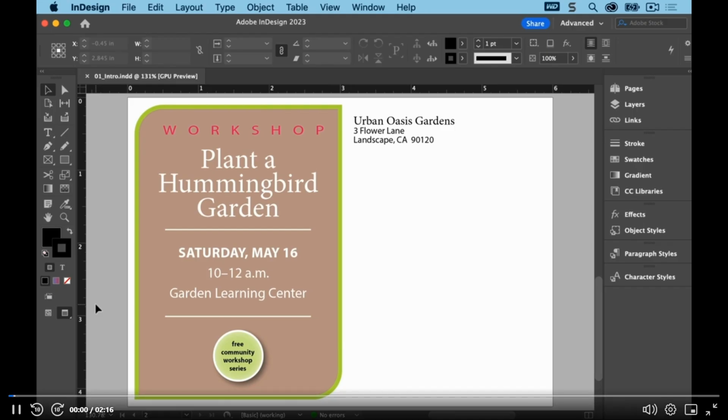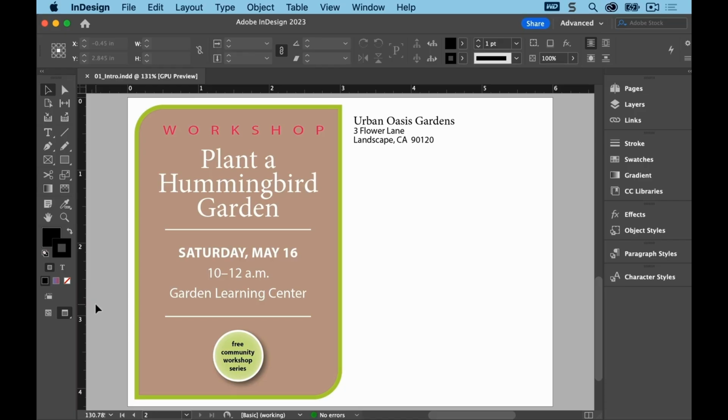You can customize the InDesign interface through preferences, including changing the overall color, the way various tools work, how the panels are configured, and how the interface scales based on screen resolution. Some settings in the Preferences dialog box affect the application, InDesign itself, whereas others affect only the active document. For example, changes to autocorrect preferences are document specific, as preferred spellings may change among clients.